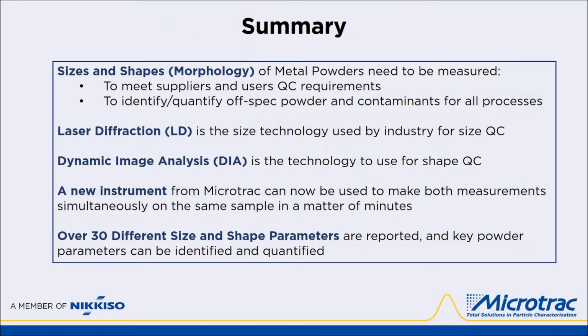In summary, sizes and shapes of metal powders need to be measured to meet suppliers' and users' QC needs, to identify and quantify contaminant particles for all processes, and to monitor recycle streams in laser melting additive manufacturing.